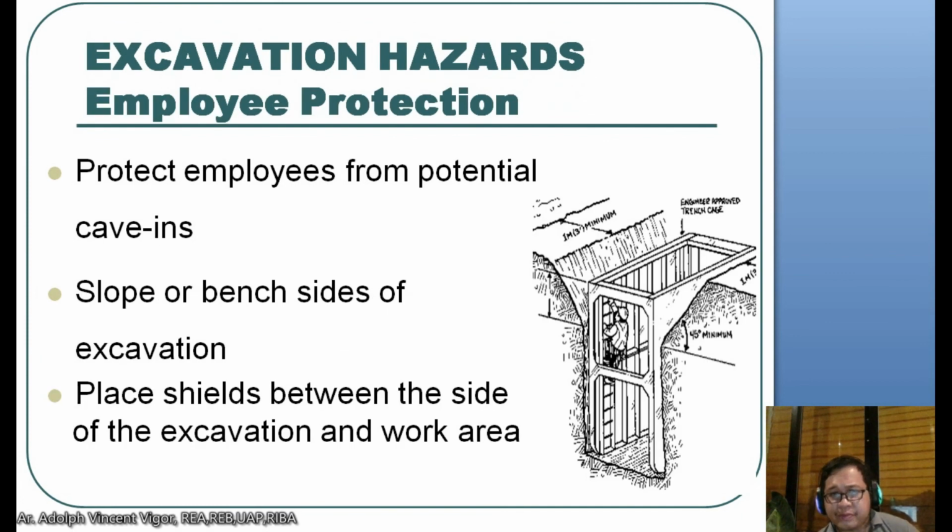To protect employees from potential cave-ins, slope or bench the sides of the excavation, and place shields between the side of the excavation and the work area. As you can see here, this is for support, so that the soil here would not just erode and fill this gap.